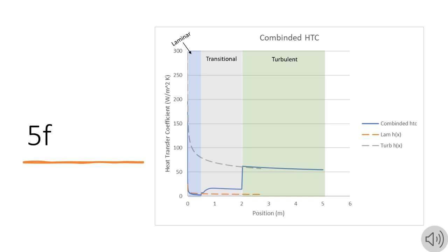However, once this peak has been reached, the heat transfer coefficient begins to drop again in the flow direction. We can see that the purely laminar and turbulent profiles indicated in the dotted lines converge with their respective flow regions on the combined profile.